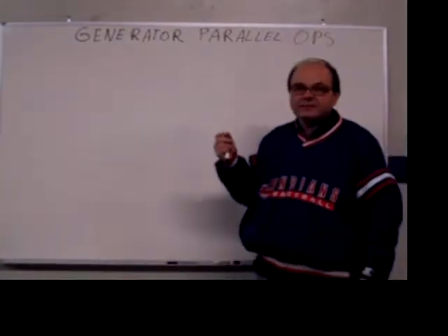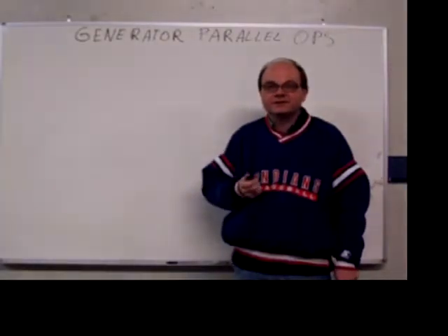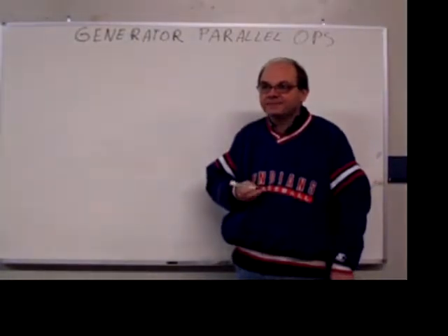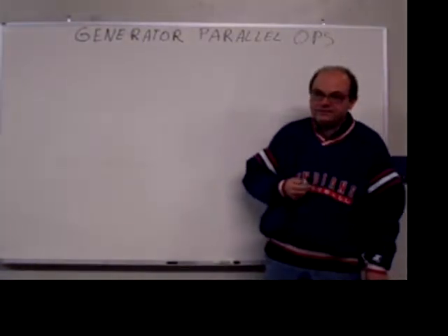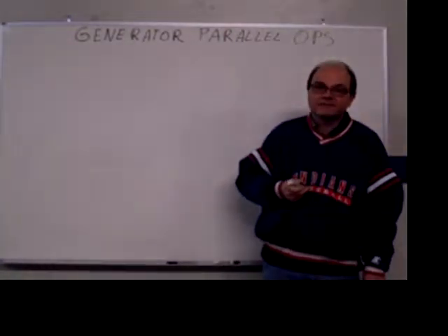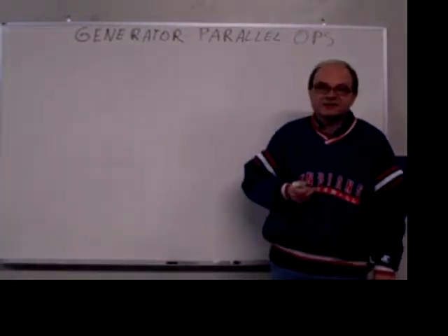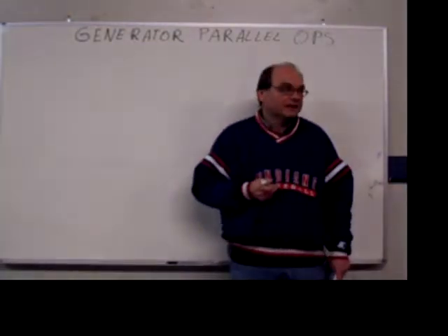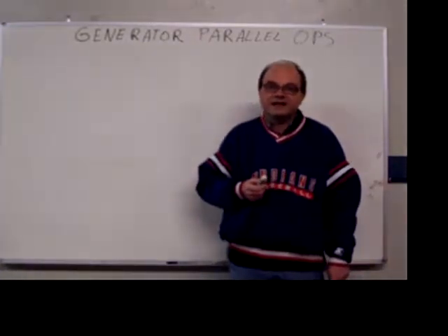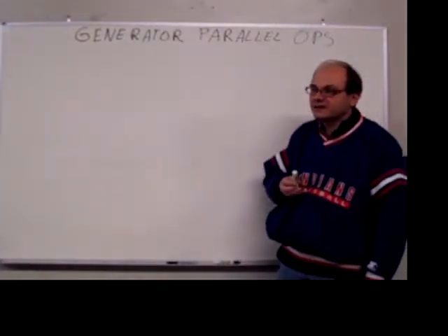I'm doing this today because I looked at these boards and watched some other videos on YouTube, at what other people did and how they paralleled their units. From a professional point of view, you can really get into trouble when you do parallel operations the way people suggest, especially on the MEP 002A and 003A, the 5 and 10 kilowatt units, since they don't have a syncing connection or control circuit involved with it. That becomes really tricky, and I will explain this.